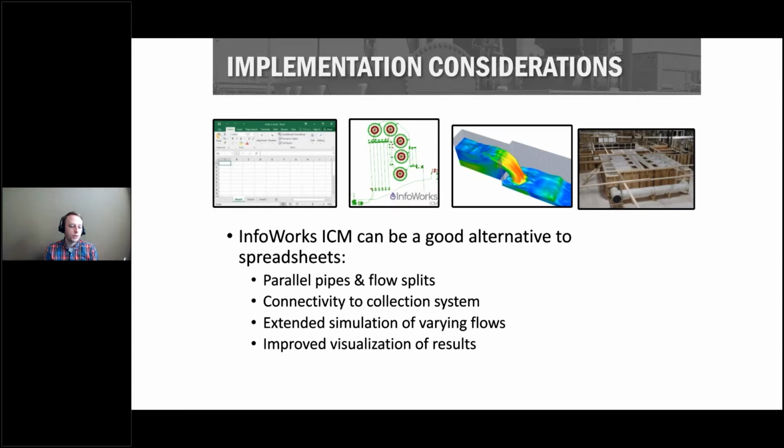At some treatment plants, the gravity collection system might go all the way through primary clarification. So what happens at the treatment plant has a direct impact to the collection system. There's not necessarily that big influent lift station up front that's maintaining a steady wet well level that the collection system sees as its downstream HGL. Instead, there are all these treatment processes that are setting that, and so that HGL can vary as flows increase through the plant.